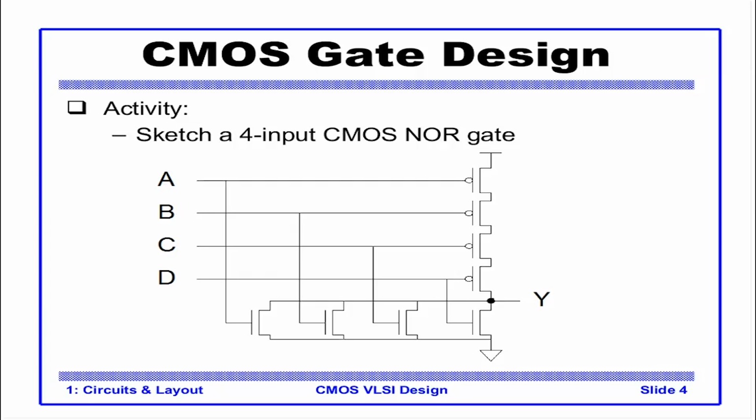Similarly, the pull up network, which is connected to VDD there, will be the complement of the NMOS of the pull down network. Since all the NMOS are in parallel, the PMOS shall be in series. So VDD is connected to PMOS 1 and PMOS 1 is connected to PMOS 2. And the output for this kind of circuit is always taken from the common drain, or whatever drain or source you want to call it.